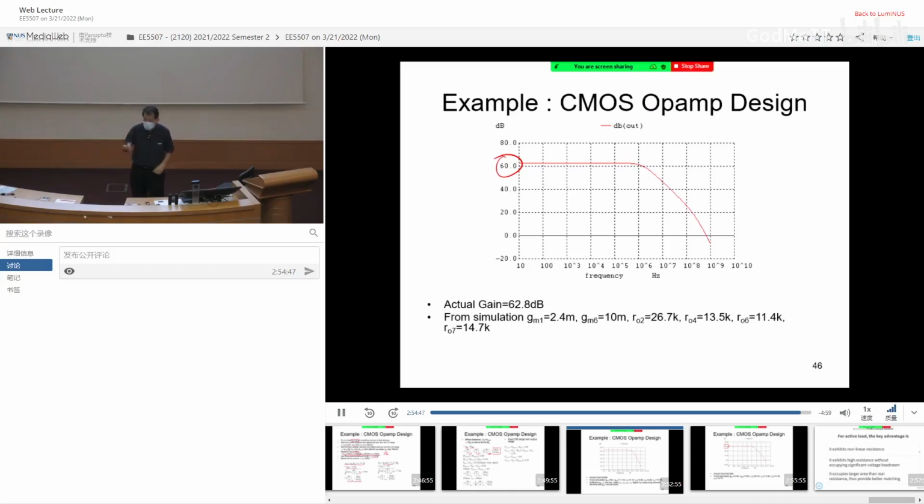Now, if you are so confused, look at cascode method 3. Cascode method 3, no need for calculation. Just intuitive understanding. VDS plus VGS, VDS plus VGS, that's it. Okay? How do you get VDS? Make one transistor very big. So the VDS becomes VGS minus VTH. Therefore VDS. So cascode method 3 is very simple.